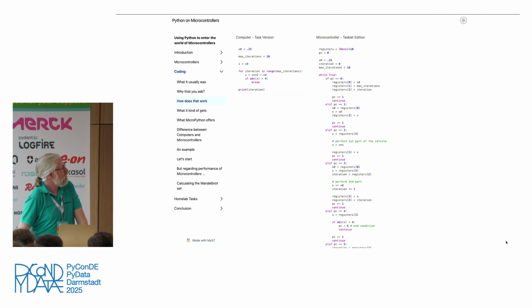And then I'm reformulating that algorithm to the left in an endless loop and looking at where I am currently with the program counter, just executing parts of my algorithm, like just loading the variables from the register so that I can use them, and in the next time cycle I'm assigning that variable to another temporary variable. In the next cycle I'm doing the squaring, in the next cycle I'm adding the original number, and then I do the compare.